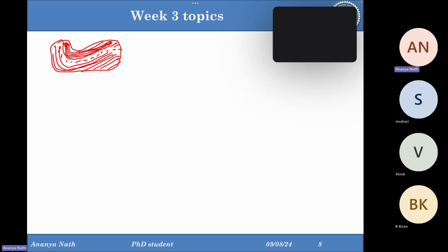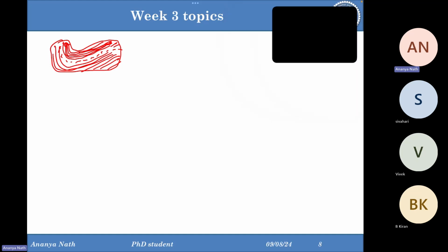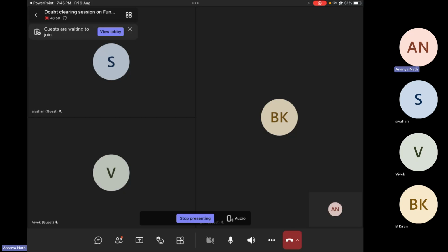Then there is one type of contour path. So basically, by using contour lines, you are filling the whole area of the object. There again, the switch on off is more, so not good. But the hatching is constant, which is good.